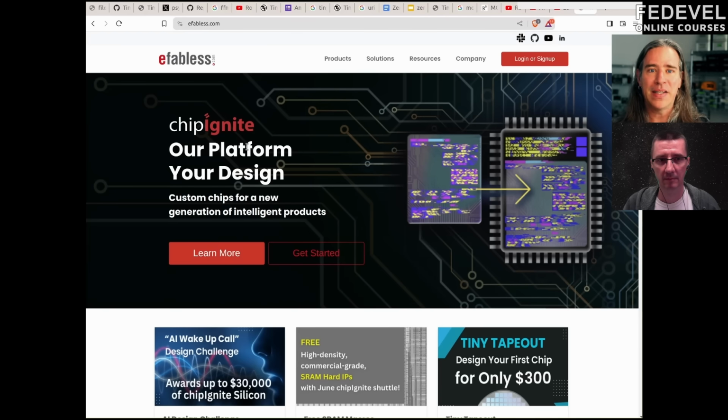And so basically we're getting closer and closer to being our own chip, but that's all developed by Tiny Tapeout, basically all that surrounding stuff that chooses between the projects, because there's a MUX there. Now, two kinds of MUXes really, but one is digital and one is analog. And you say, hey, I would like to talk to project number 265. It shoots all the IO to the correct project. Power gating turns on if it's analog or something like that. So all that infrastructure is basically what Tiny Tapeout has done on top of all the actions and the infrastructure to make it easy.